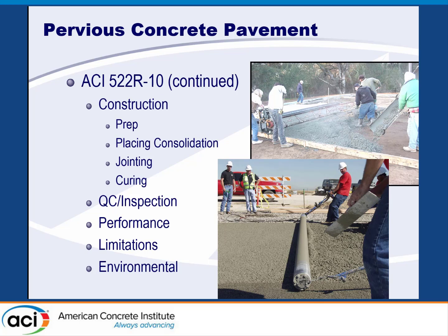It also talks about jointing and curing of this, curing being very important to make sure that we get the strength that we need and that this structure doesn't just crumble and can actually carry that load. So it also goes through performance. It also goes through some of the limitations with this type of pavement and what you need to do to make sure it performs, where a lot of times we need to make sure that it doesn't get clogged up with debris from the underlying section, the subbase and substructure, clogging up the void structure within it, to make sure that it can still take in that moisture and that water.